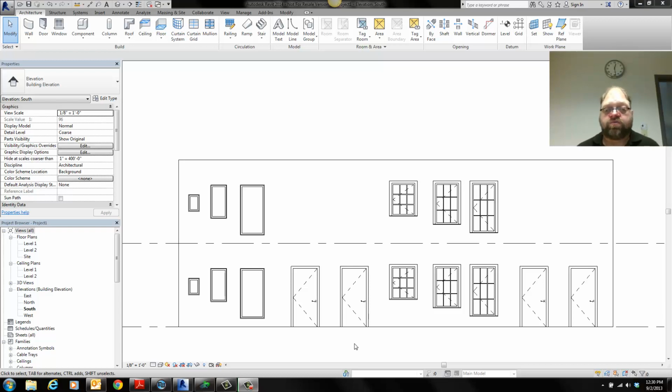Okay, so today, this is our week 3 lecture, and last week we talked about the hierarchy of the objects that exist in Revit. If you remember, the hierarchy that I described back then is at the top we have category, and then underneath we have family, and then under that we have type, and under that we have instance.